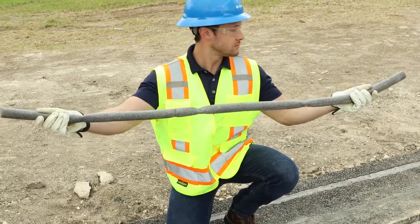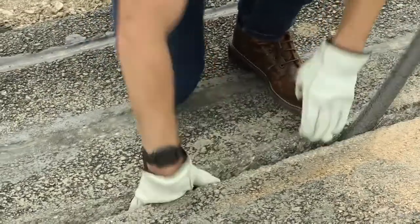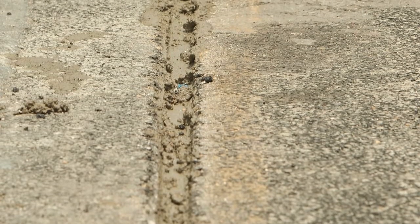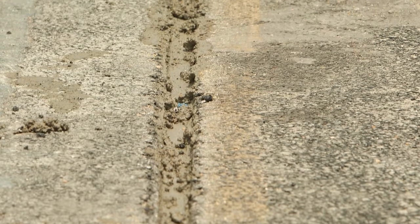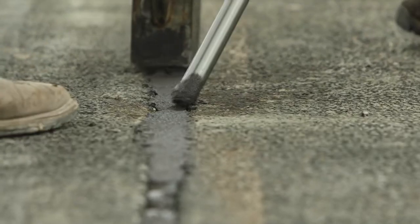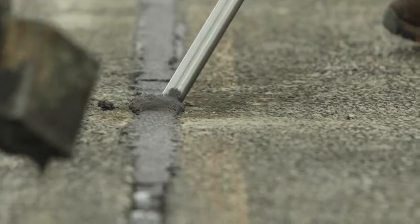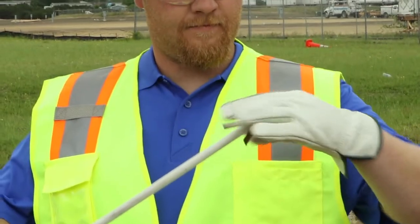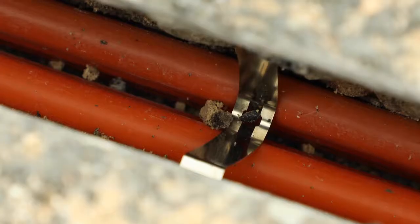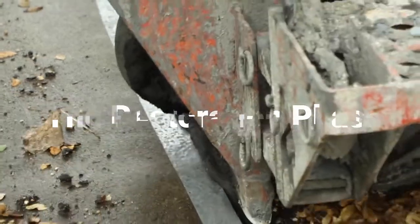Prior to restoration placement, it is recommended to place a layer of sand or foam backer rod. A 1-inch layer of sand or flowable fill will serve as insulation and can also help anchor the conduit if a liquid reinstatement material is utilized. Sand can also serve as an insulator if hot asphalt is used as the reinstatement material. If a fluid reinstatement material will be used, such as a flowable grout, it's advisable to anchor the conduit into the trench. Step 4. Restoration phase.